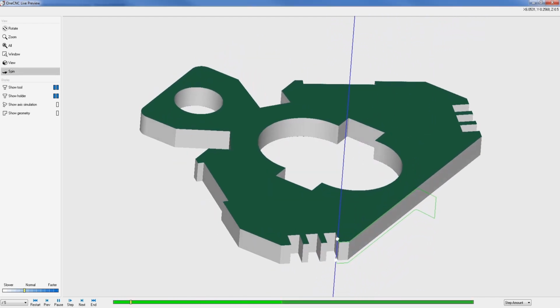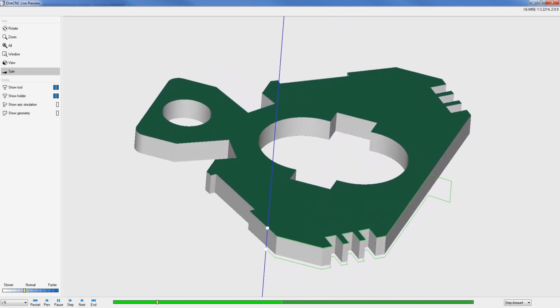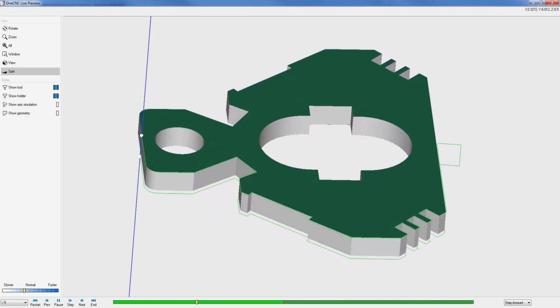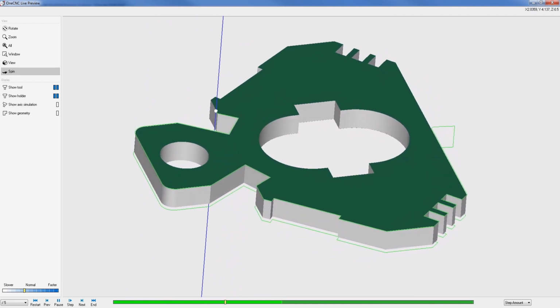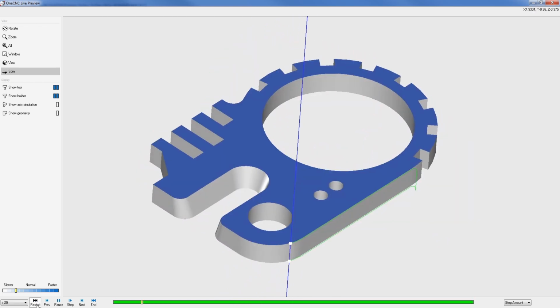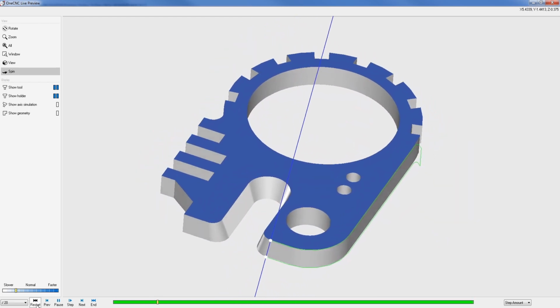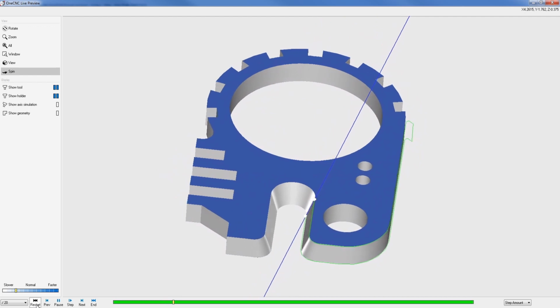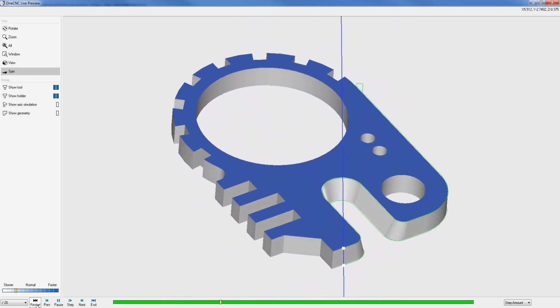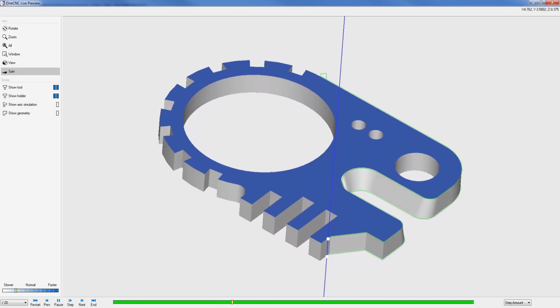OneCNC 2-axis wire provides the ability to apply wire cuts to both open and closed profiles. Critical parameters such as wire compensation, cutoff, blending, auto-threading are easily defined and implemented. OneCNC 4-axis wire adds the ability to apply wire cuts to complex geometry. Geometry can be defined as wireframe, solids, and/or surfaces.